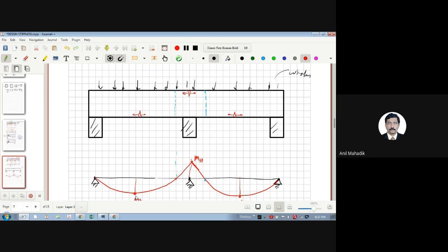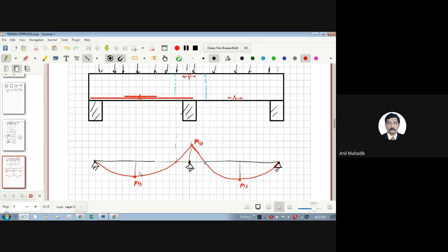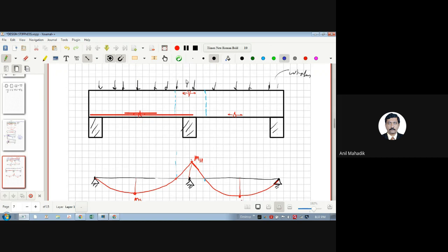So maximum steel should be at the center. And as there is a complete tension here, I will provide bottom tension here. So let's provide the steel like this. And I will provide here more, means at the center moment is more. So this is the design for this. Now top, you don't need ideally any, but to hold the stirrups, I want this blue color.